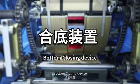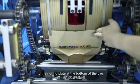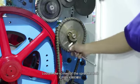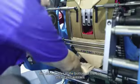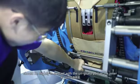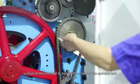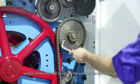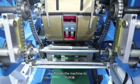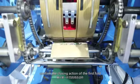Button closing device. Rotate the machine so that the first fold is close to the closing plate at the bottom of the bag. Loosen the screws of the sprocket hub. The closing roller at the bottom of the bag should be slightly in contact with the unglued part of the inner surface of the first fold. Tighten the screws of the sprocket hub. Rotate the machine to confirm the closing action of the first fold.